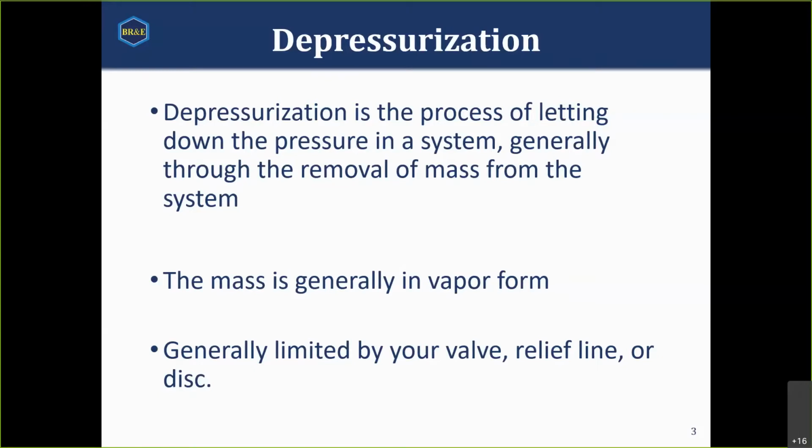Generally, when we talk about vessel depressurization, we're talking about vapor, but it does not have to be. There are a number of other methods of relieving the pressure. One method that you do see with some frequency is something called a thermal expansion valve. That's usually when you have a liquid line and you are expecting some sort of thermal expansion due to temperature, and so you have a very small relief valve to allow that liquid to come out. Usually that relief valve is very small.